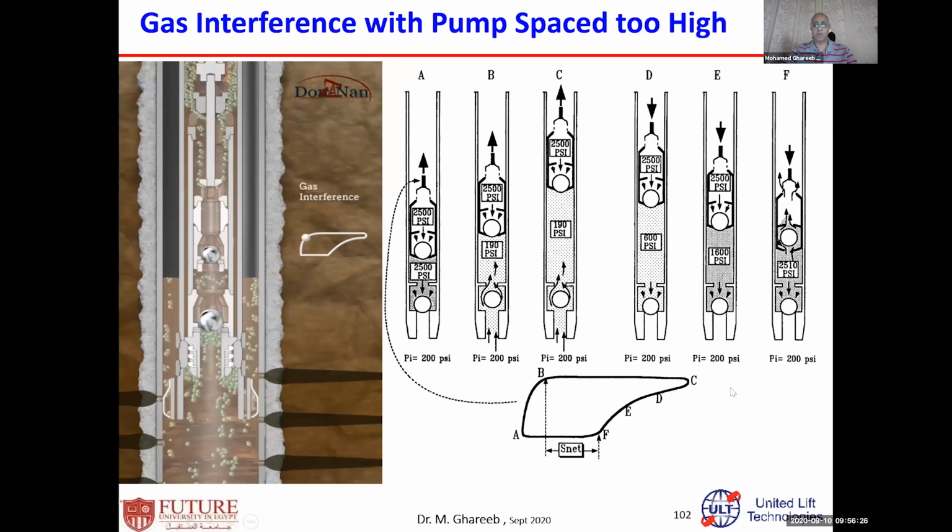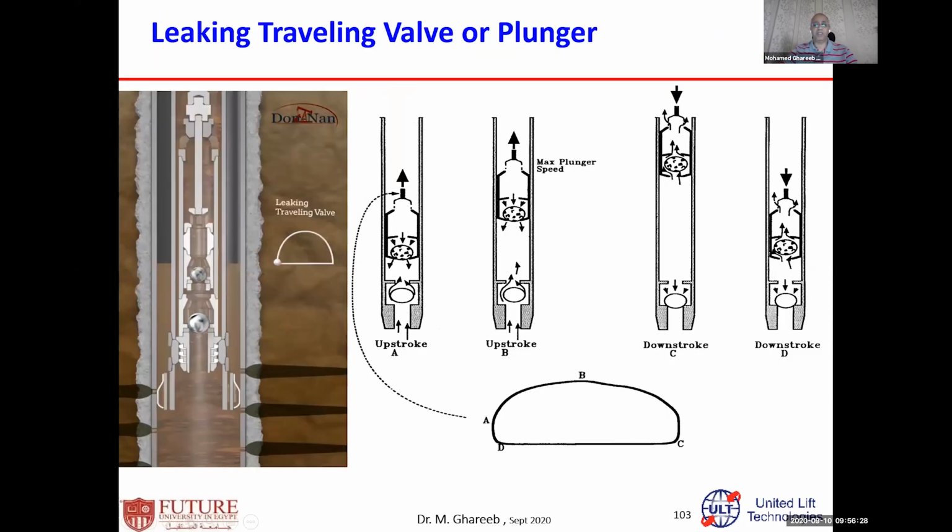Okay. What about valves? If I have a problem with a valve and some valve leaks, look at these valves. You have some pitting, some problems, and so on. While I'm going up, this valve should hold the fluid, should hold the load. But since you have some leaks, a part of this fluid will be leaking down again. Yes, it holds a part of the fluid and moves up, because it holds a part of the fluid moving up.